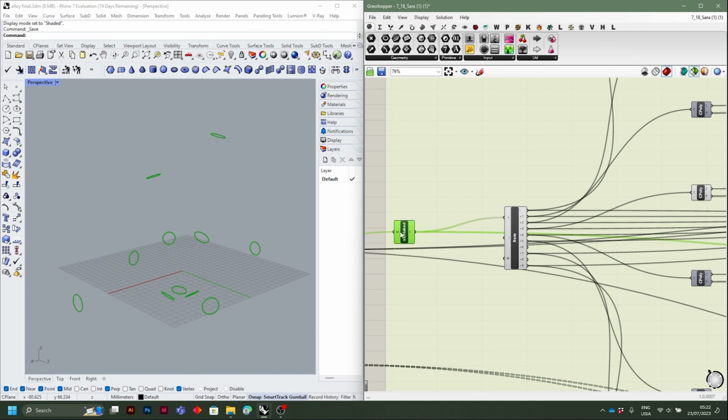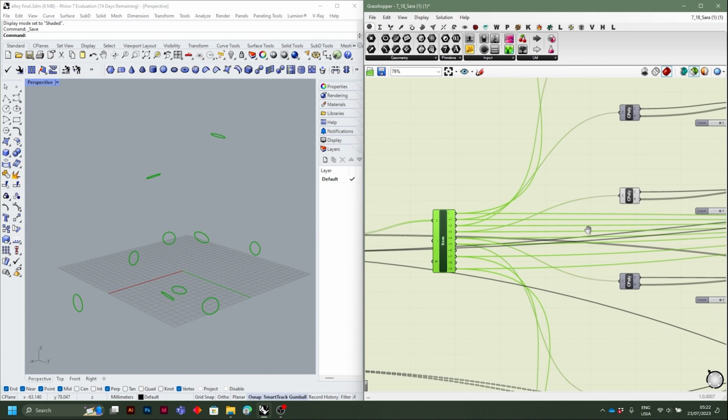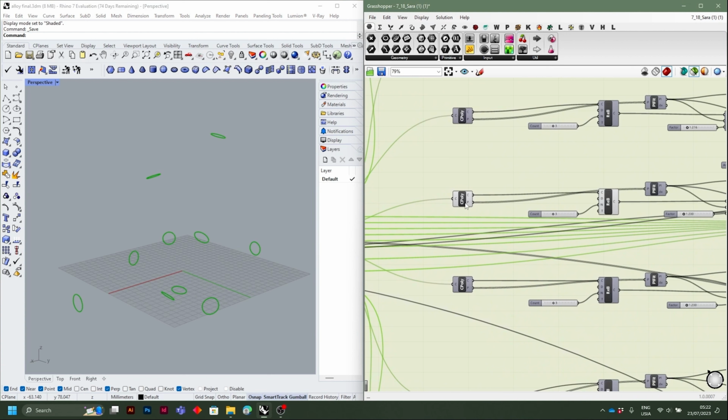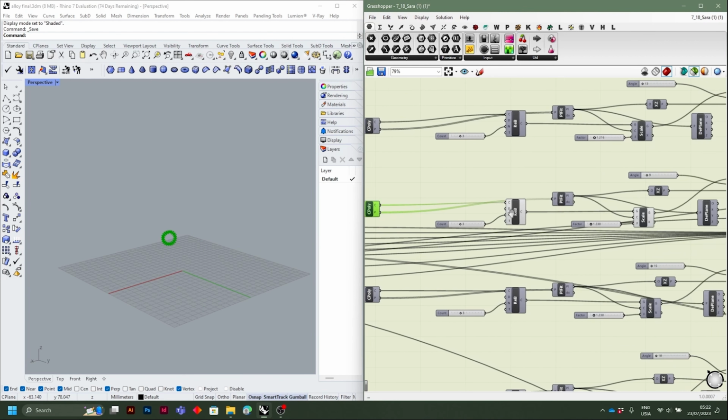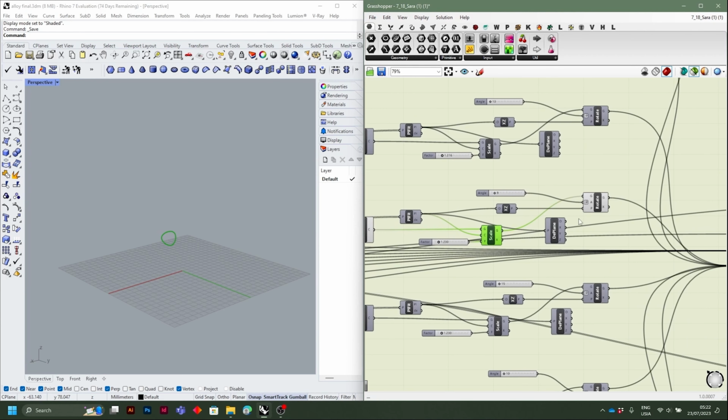So to achieve that, I used Weaverbird naked edges and extracted specific edges as I didn't want to deform the bottom of the vertical pipes. So after selecting the edges desired, I extracted the control polygon for each curve, rebuilt it, scaled it, and then rotated it.